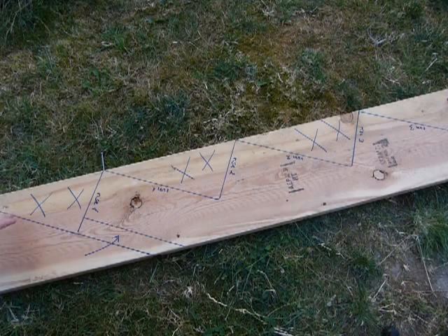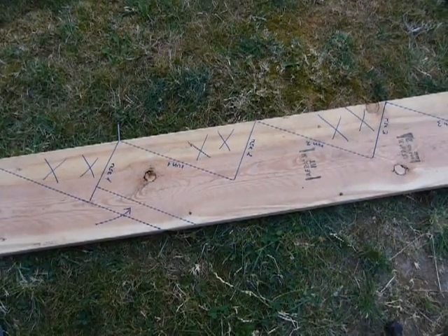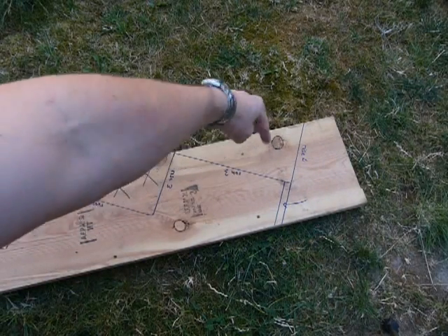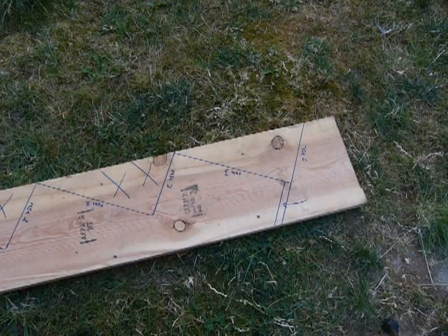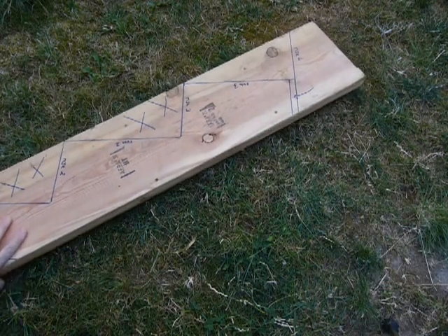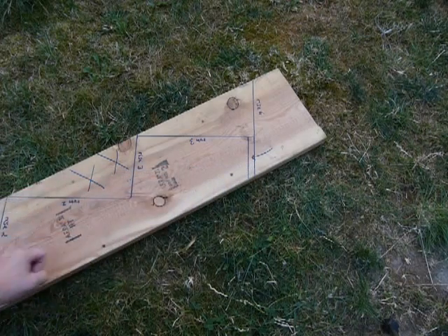As I said before, I extended this first run here to get me a plumb cut, sorry guys, and I also extended my fourth riser down to get me my, sorry, that first one was the level cut and that's my plumb cut. So the stair will work this way, and the shortenings are here. This little bit here is a shortening.